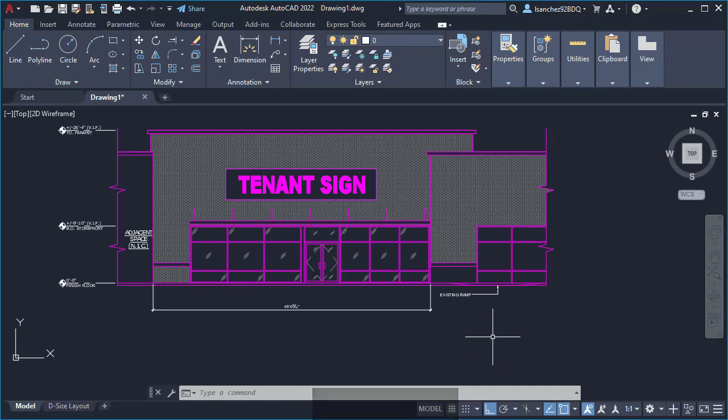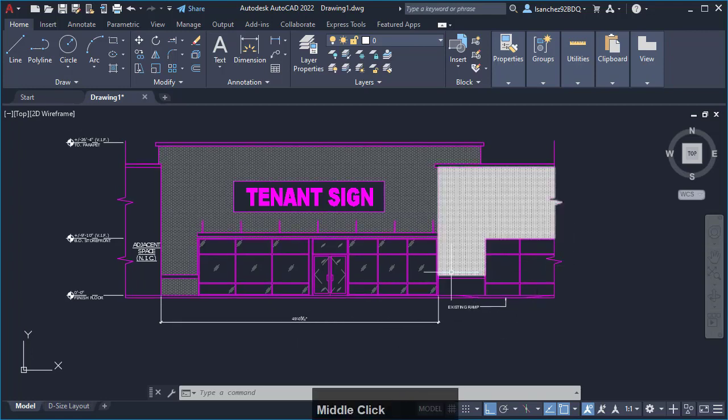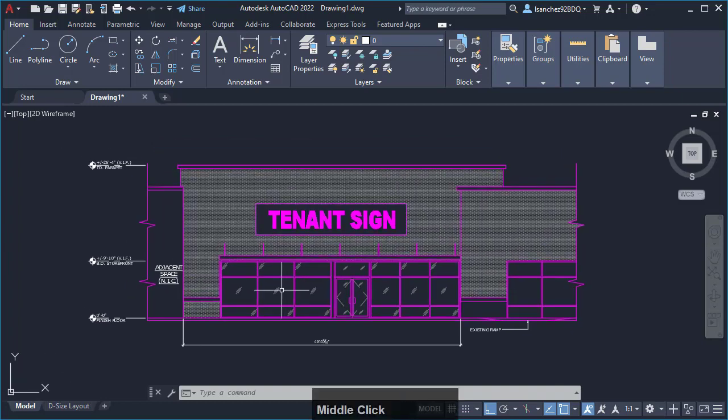layers. Layers, it's a very important concept in AutoCAD, and basically layers, in the same way that the ribbon organizes the commands or tools to make your life easier and put them on each specific panel, layers organize not your commands but your objects, your lines, your text, everything, so you can have more control to modify things quicker.